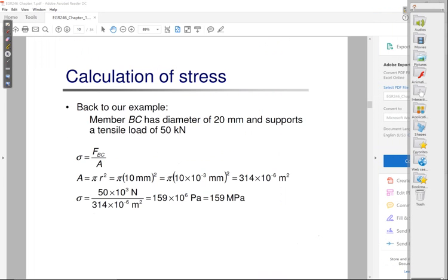324 megapascals. Let's write that down: 324 MPa. And that value is what we refer to as sigma subscript ULT, for ultimate. It's what we call an ultimate strength. On that table that we just pulled up, it was referred to as tensile strength because they tested it in tension rather than in compression. But for a lot of different materials, the tensile values and the compressive values are almost the same. So in a lot of textbooks, that's just referred to as an ultimate strength, or an ultimate stress. Ultimate simply means that it's the stress at which it breaks.